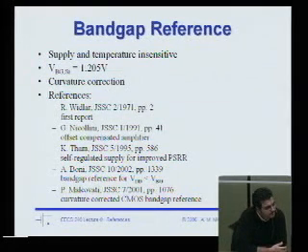You know, because external might introduce some more connection problems. I don't know. Why don't you just make a very large on-chip resistor? Well, on chip, the resistivity varies over process, right? So not just the W/L, but also the resistivity, right? Yeah, the resistivity varies a lot.